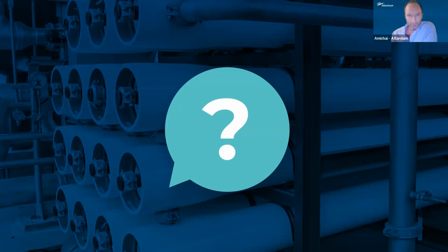But generally, the solution we are proposing is for pre-RO membrane. Okay, thank you. We have an additional question. I'm currently using sodium bisulfite for dechlorination, and I'm using ORP and pH meters for process control. Will I still need them when switching to UV dechlorination? Yes, the answer is yes. It is recommended to keep the same monitoring process as you have. For the ORP, you will need to readjust the alarm set points. If you were using SMBS, the safe ORP level might change, and this is something I'm sure ORP meter providers ask users to do from time to time.